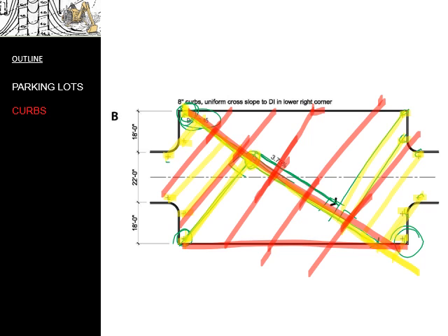And in this case, I'm going to highlight this is an 8-inch curb. So that means you will not be running halfway across. You'll be running a different length, and you will need to calculate what that length is that you'll need to run along that curb before you then come off of that curb with the contour lines.